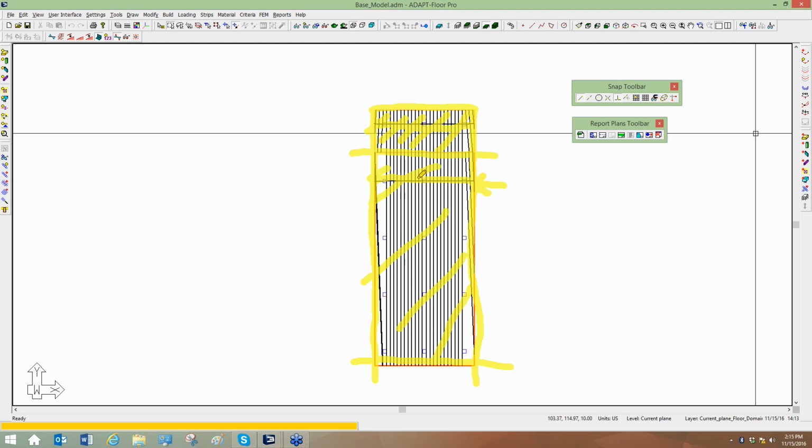And obviously this would be incorrect when you're integrating over the finite elements. You don't want to integrate over that long of an integration path, if you will. So this would be incorrect, and this happens sometimes if the user misinputs or doesn't snap to the slab edge or doesn't include splitters, or there's various reasons why this would occur, but here this just simply occurred because I don't have support lines there, or there, or there, or I don't have a splitter.